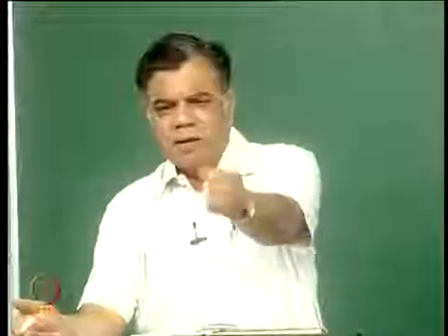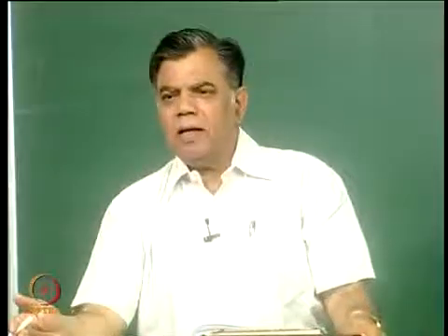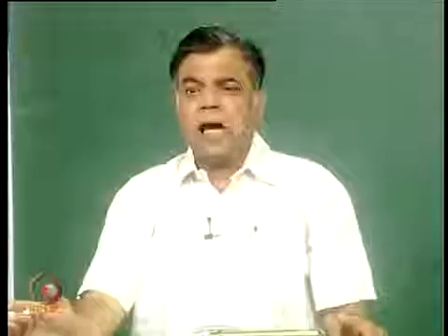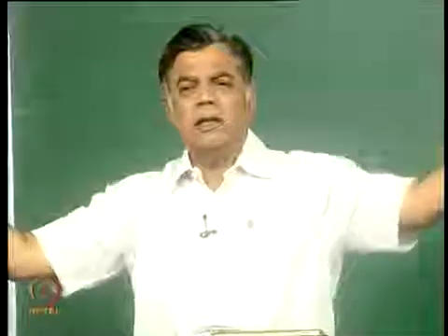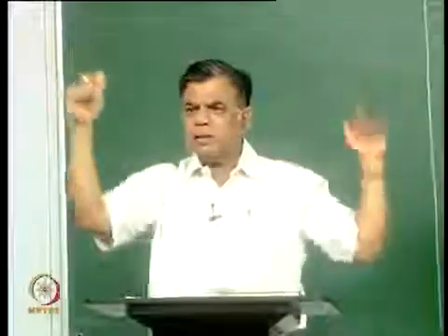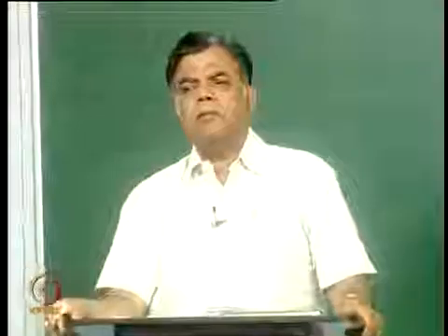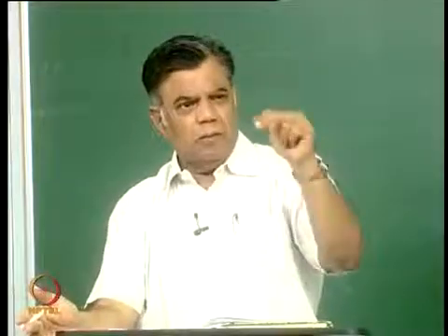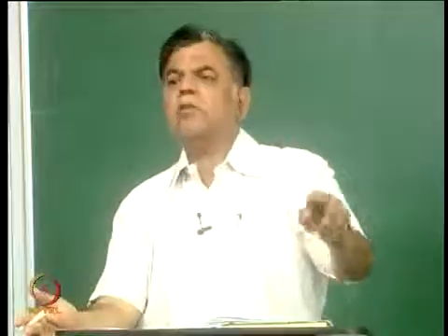So making assumptions and simplifications was a necessity at that time, and this apparently simple problem you can make into a 3-dimensional thing if you do not put in that del by del x tends to 0, del by del z tends to 0. It becomes a solution starting from the leading edge to the trailing edge and the two sides. What you have done is, I will not worry about the flow near the edges. Even when you do the experiments, you will see near the edges there is 2-dimensionality, 3-dimensionality. What you think is a 1-dimensional flow will have 2-dimensionality. What you think is a 2-dimensional flow is 3-dimensional.